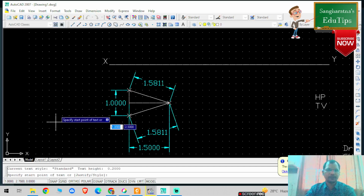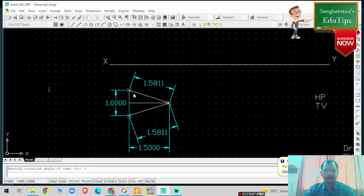Select any point here on the screen. I am specifying the height as 0.21 and rotation angle is 0 due to the complexity of the figure. So this is particular point A, this is my point B, this is my point C. And this is basically my true shape. So once you have drawn the true shape, you are going to project the lines perpendicular to XY.